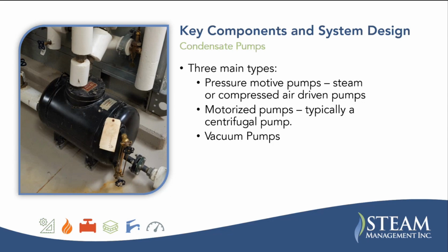And then vacuum pumps. So vacuum pumps are a unique piece of equipment that basically you're pulling on the steam system instead of pushing into the steam system, creating a vacuum. This helps return condensate to the boiler.